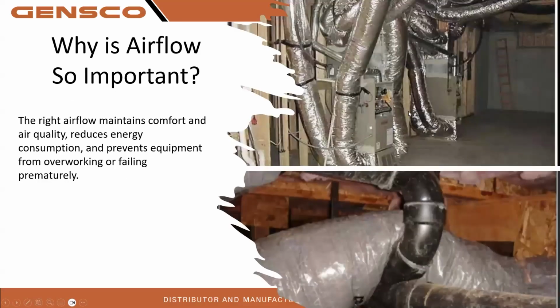So please, I hope this doesn't look too familiar for us unless we're there to make it right. But these are all far too common systems that we see out there, especially when we start utilizing flex duct. Flex duct is a great product used in the right scenarios. When you see flex duct, it is restrictive. Think about going down a slide as a kid. If we added a whole bunch of bumps and ribs to that slide, it is going to be a lot harder for you to go down that slide than if it was slick and smooth and you were able to just scoot down that thing. Same thing with airflow going through ductwork.